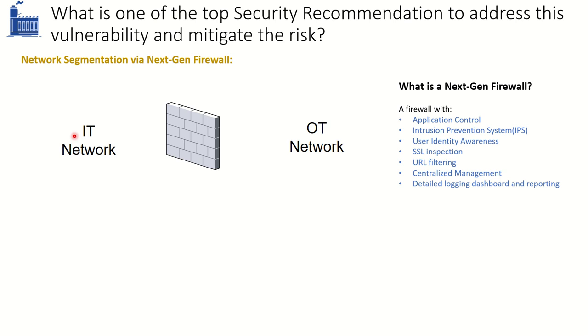What I mean is that if you have vulnerability assessments or penetration tests going on in the IT network, then there is a lot of broadcast traffic in the IT network, such as ARP protocol traffic, and the OT devices are not very adjustable to this broadcast type of traffic, to this huge size of traffic, and that is the reason they can fail, they can start to malfunction.